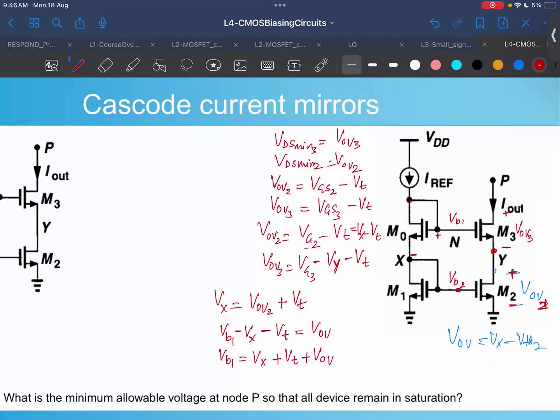So that means now if we were to see this, you clearly see that the value you get here is 2, because if we put the Vx value, so what I'm taking here is VOV, because it's the same transistor. Because the current is the same in both the transistors, VOV is the same and the W/L is the same. So that means this comes out to be 2 VOV